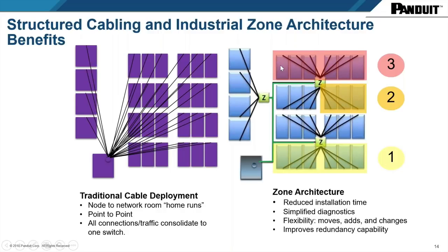And inside the cell, you will then have to worry about the MICE rating. That makes it a very efficient way of distributing the network. If a certain cable is broken inside of a cell, you're affecting just the one area in the cell. You will not be shutting down all of these different areas to run a cable from the central system to the affected zone. So these are ways of running a network inside of a factory where you have to really consider the zone, the MICE rating, where you have to really consider the architecture, where you try to optimize the cost of your cabling and connectivity.